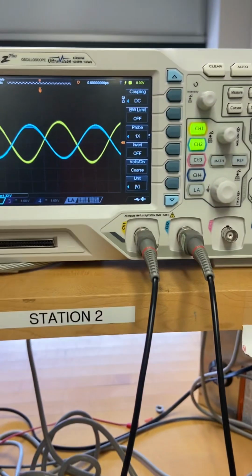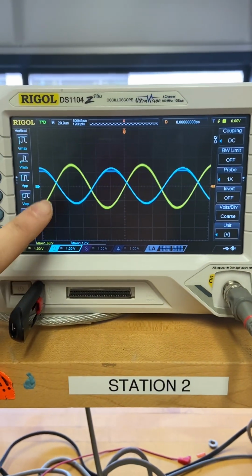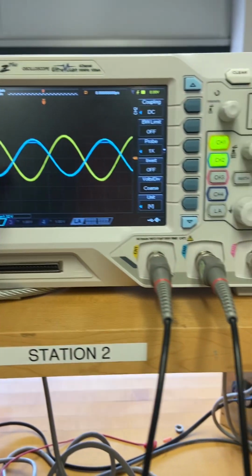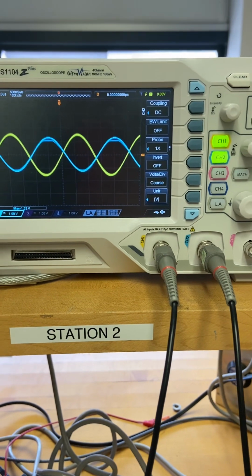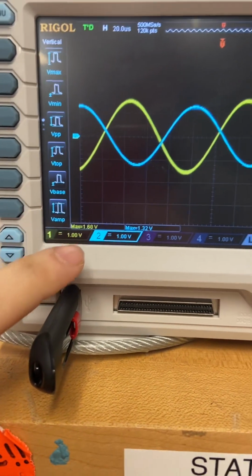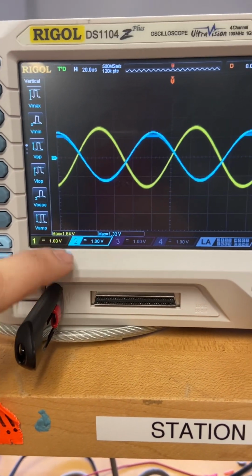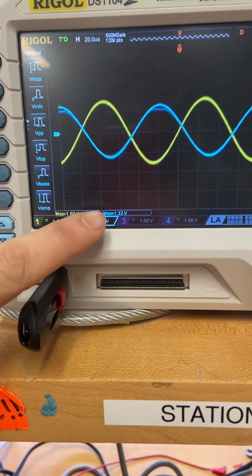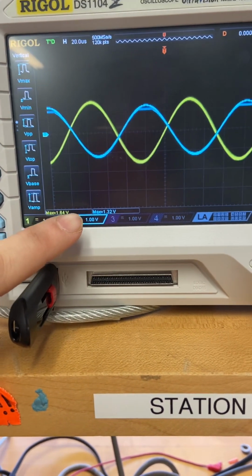These oscilloscope probes create some noise in this oscilloscope, as you can see in the image. They're pretty noisy, but these are the only ones available in the open lab, and I've tried to calibrate them as best as possible. But back to the Vmaxes, we can see that it's about 1.64 to 1.3. If you do 1.60 divided by 1.3, it's about 0.81.